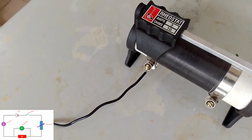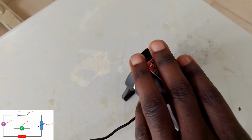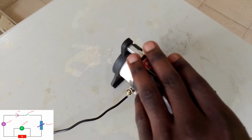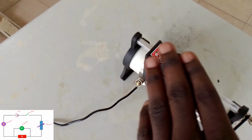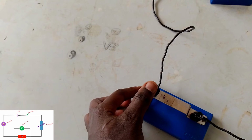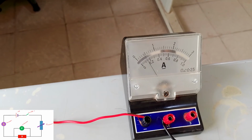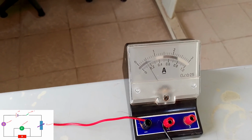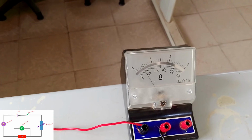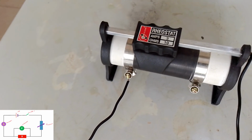Remember, in this procedure, what you have to do is you set the rheostat to a certain value of resistance. The importance of a rheostat is to either increase the resistance in the circuit or reduce the resistance in the circuit. So when you set it to a suitable value, let us see what happens when you close the switch. You can see that now the ammeter reading drops to around 0.18, simply because you have increased the resistance in the circuit.